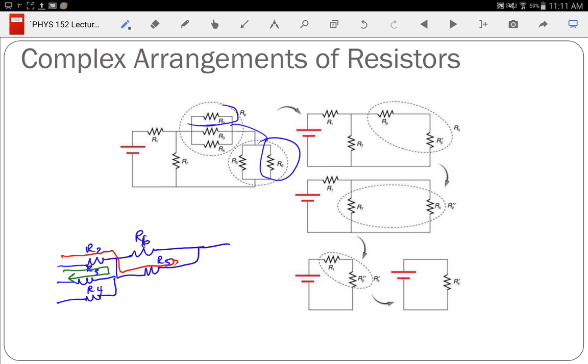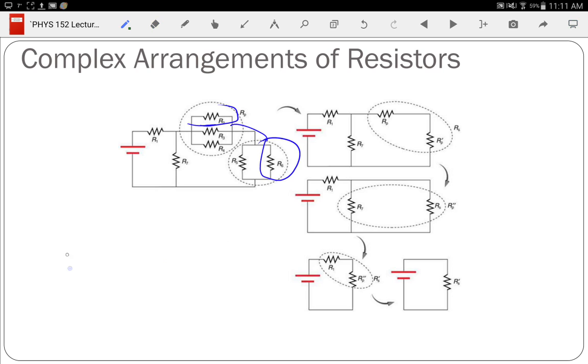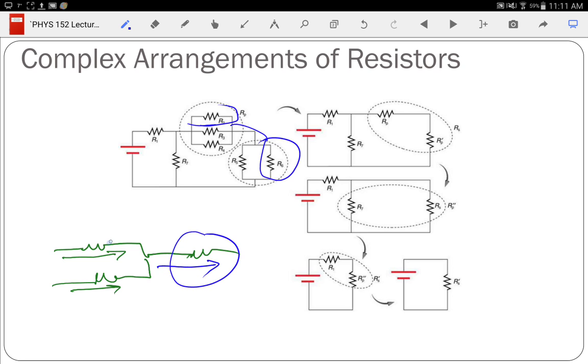But it's still possible. Or to put it another way, the way you're thinking, Chad, is if I only had one resistor here. I'm just going to rewrite it. I'm just going to write 2 and 1. If it's like this, current going like that is going to merge to go through here. And so the current that goes through here could have come from here or here. For them to be in series, there has to be only one option. That's 2 options.